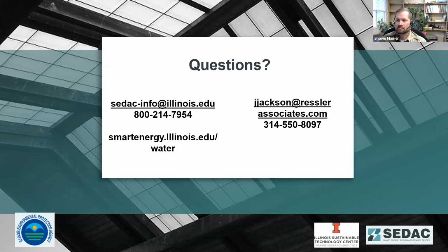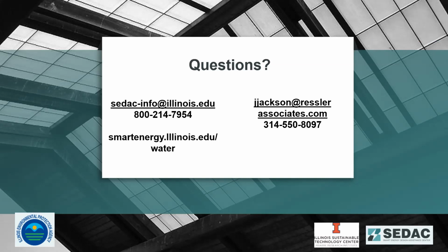But if you're going to be doing some of this advanced analysis and data trending, trying to forecast future flows and stuff, you'll want to have a few years of data stored in a historian. I would recommend as much as you can. Yeah. Save as much data as possible. If you don't have the capability of storing it, I understand, but otherwise that data is priceless, especially moving forward into the future. If we want to do upgrades and things like that, engineers absolutely love having data to be able to move forward.